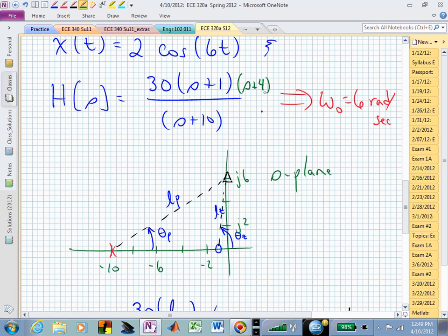That was an s plus 4, and so that gave us that right there, and this would give us a different length. And all of those factors, then, we look at the magnitudes, their lengths will be multiplied or divided if they're zeros or poles, and their angles will be added or subtracted. Does that make sense? So we add and subtract angles, we multiply and divide magnitudes or lengths for all of the factors that we might have.